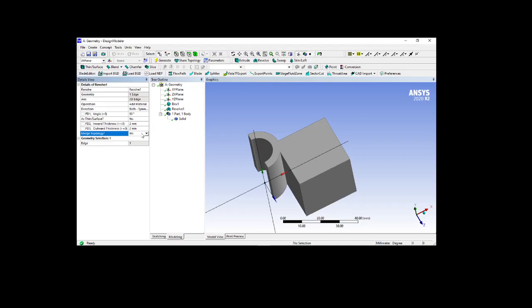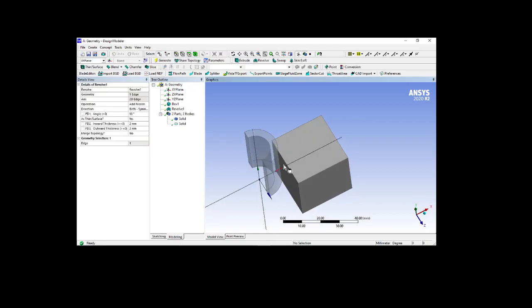Here also the same. If you merge this topology into the body, you can. If you do not want, just press the no key and generate. Then this geometry is entirely different from the other. Okay, since this is the add material, if you give frozen, this is how it will be. Now if you press this, this is another body, and this is a different body. Okay, so I will delete it.